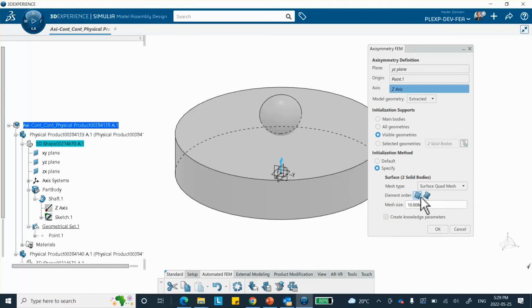And finally, it says what is the size. Okay, I'm going to use, first of all, bilinear, meaning a bilinear element with a size of 0.3. The reason I use 0.3 is because it's compatible with that link that I showed you on the ABAQUS CAE version of this particular tutorial. He's using 0.3, I'm using 0.3. We say okay, and just give it 1 second, maybe more than 1 second.